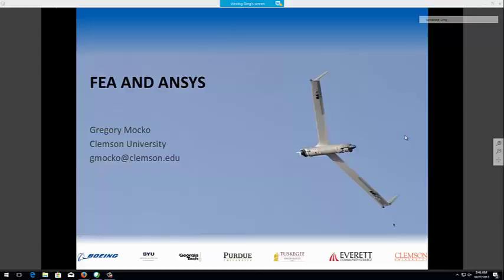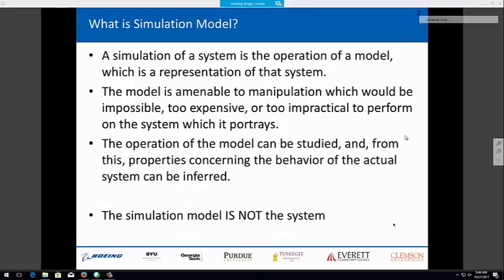The other aspect of that was he had a tube that was pinned on one end and a load on the other end, which looks like a cantilever beam to me. Instead of running a finite element model, he could have just done this in 32 seconds with Euler-Bernoulli beam theory and sort of minimized his level of frustration.